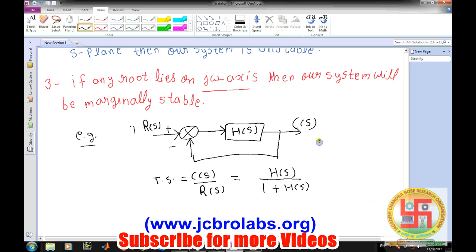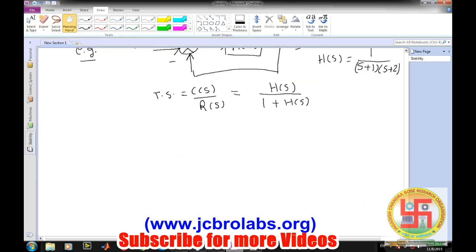Then let's say we have been given H(S) equals 1 divided by (S plus 1)(S plus 2), and we want to know whether this closed loop system is stable or not. So from our understanding of what we have learned so far, the transfer function of the system will be 1 divided by (S plus 1)(S plus 2) plus 1.